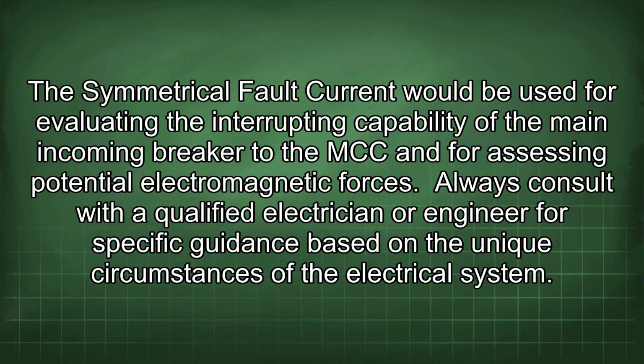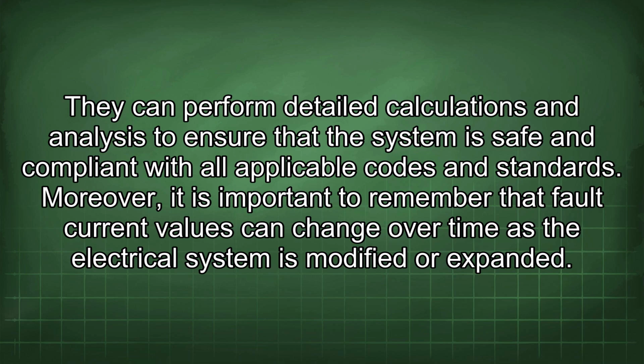The symmetrical fault current would be used for evaluating the interrupting capability of the main incoming breaker to the MCC and for assessing potential electromagnetic forces. Always consult with a qualified electrician or engineer for specific guidance based on the unique circumstances of the electrical system. They can perform detailed calculations and analysis to ensure that the system is safe and compliant with all applicable codes and standards.